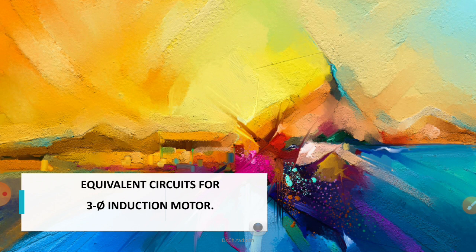In the secondary of a transformer, the energy is entirely electrical in nature, the electrical power, which is given to our electrical loads like ceiling fans, tube lights, etc. Whereas in the motor, the AC supply is given to the stator winding. It establishes a magnetic field similar to the transformer, but it is linked with the rotor winding.